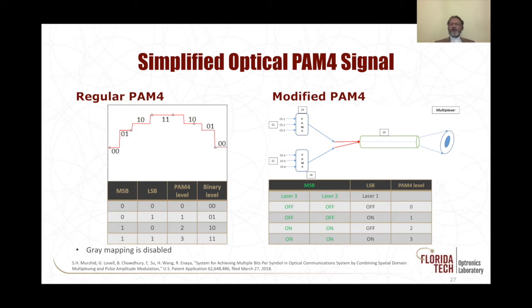The beauty is that they do not interfere with each other. As we already demonstrated in SDM, multiple channels of light of exactly the same wavelength propagate through the fiber without interfering with each other, and we basically proved the same thing again. So if I could do that, I can have these three PAM4 signals coming at an SDM channel here and at another one at a different angle. Then I can have OAM associated with these because of the different angles, and in each of them I can have the entire C band running. That is the whole game plan, folks.